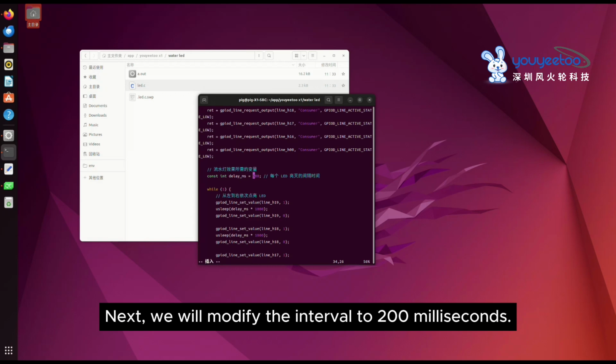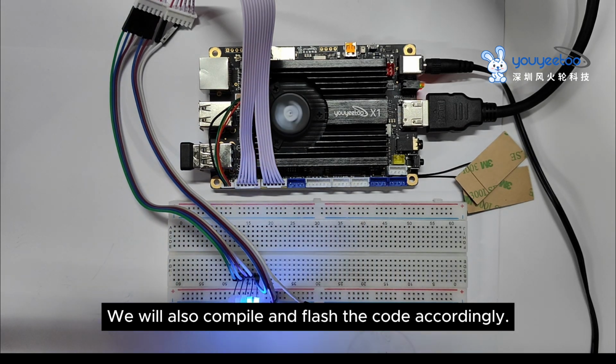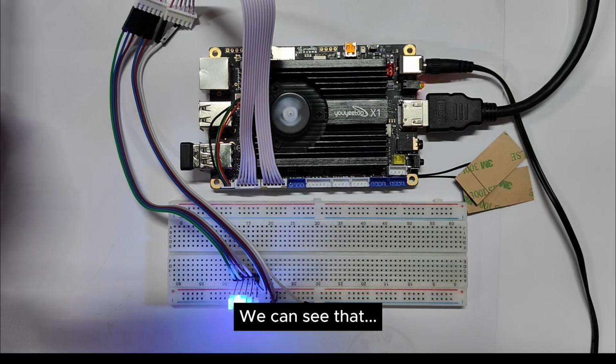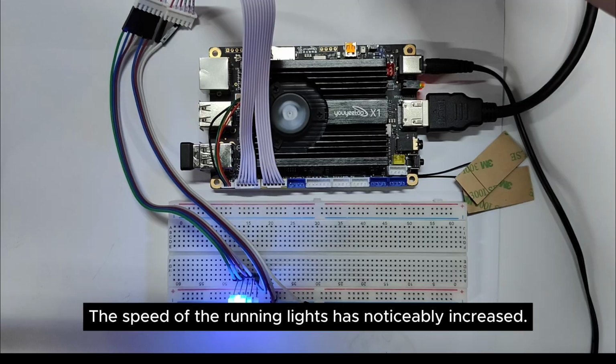Next, we will modify the interval to 200 milliseconds. We will also compile and flash the code accordingly. This is the running light effect with a 200 millisecond interval. We can see that the speed of the running lights has noticeably increased.